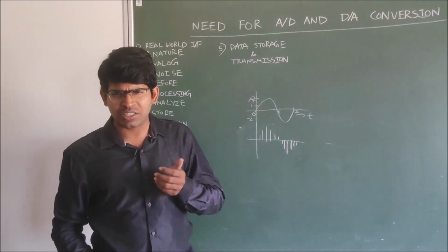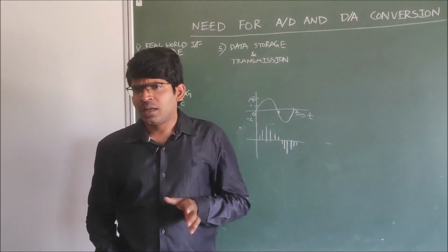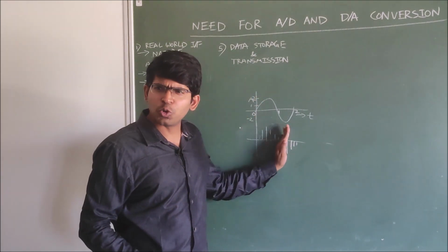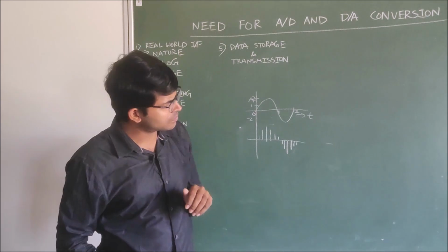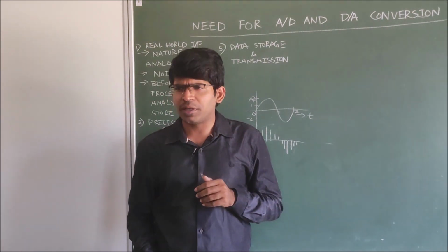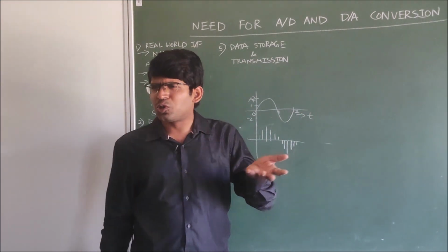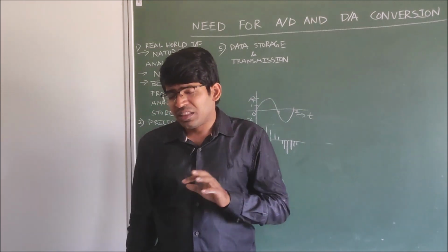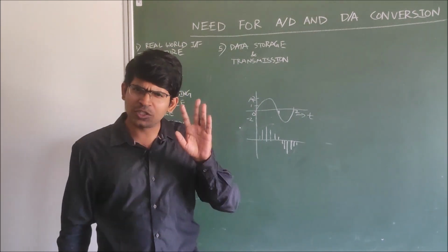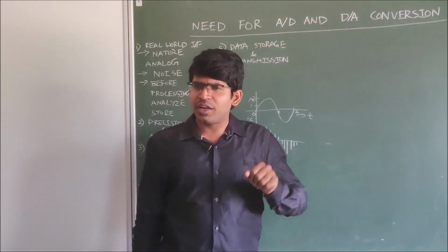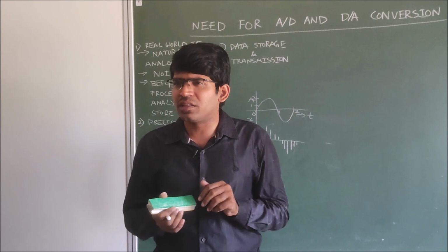This was told by Nyquist. If the maximum frequency is f, then how many samples do you have to take? A minimum of 2f samples in order to reconstruct the signal. That is what you might have studied in the sampling theorem. So Nyquist told us there is no need to store these infinite samples, no need to transmit these infinite samples in the time domain. Instead of infinite, I will reduce the number. For that I am telling you one sampling theorem.